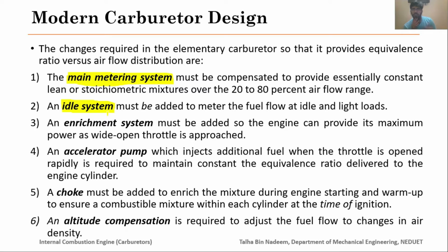When you are operating your engine under idling conditions, there is no load, but you basically require a rich air fuel mixture to overcome the friction between the stationary components of the IC engine.